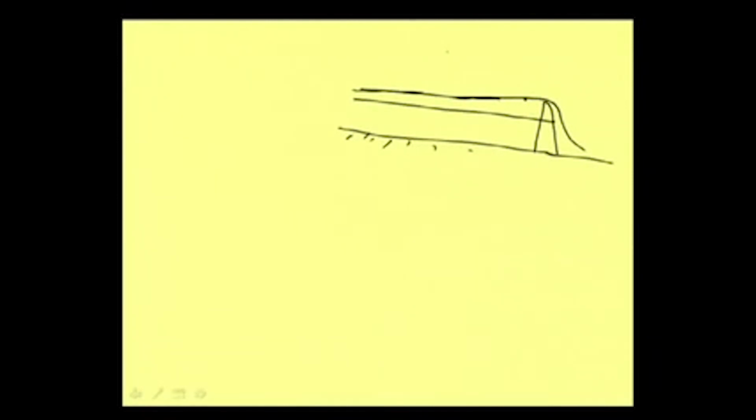That means when water will be flowing from this level, we can carry the water. Let me draw a cross section. Suppose this is the river, generally the slope will be in this direction and say our water is here. Now, if our water level is here, we cannot carry the water up to a certain distance, but if we increase our water level up to this much height, then we can carry it by gravity, suppose making a channel, up to this level where our level meets this point.